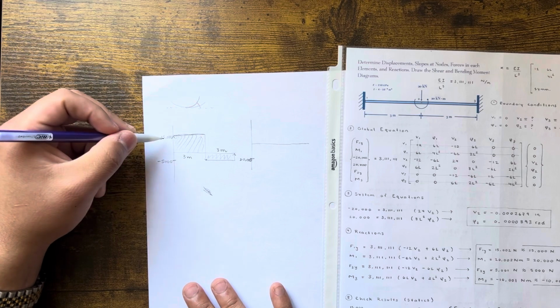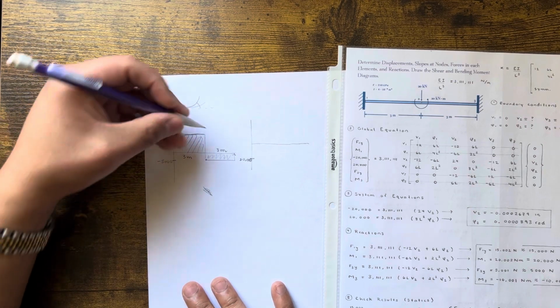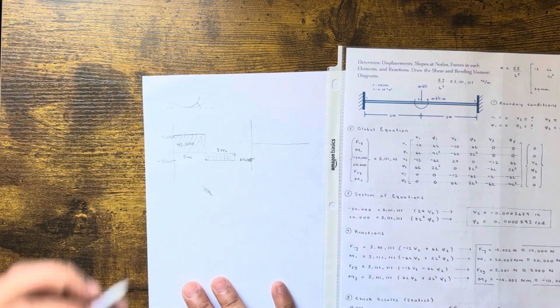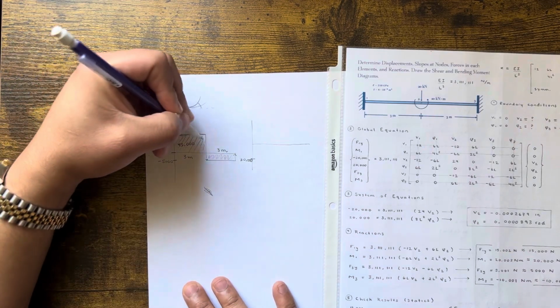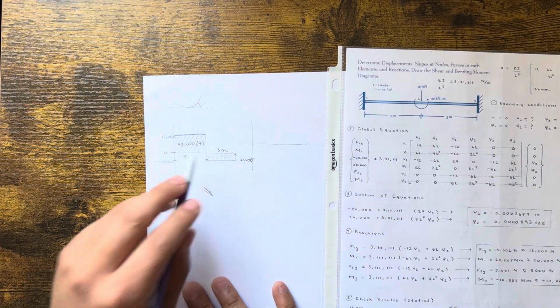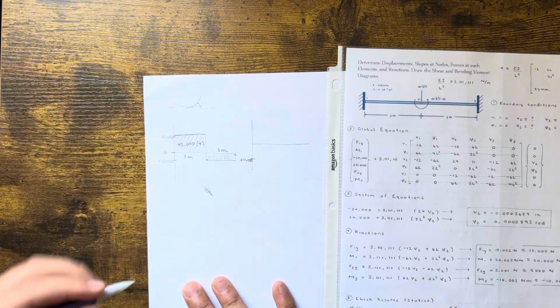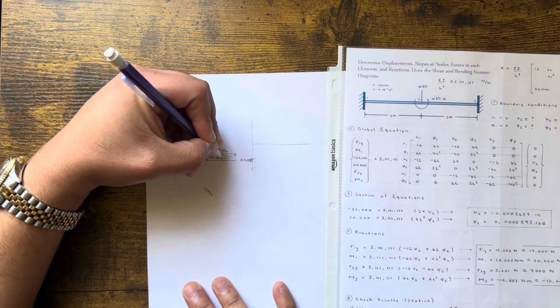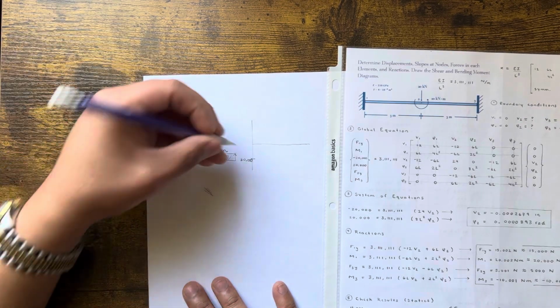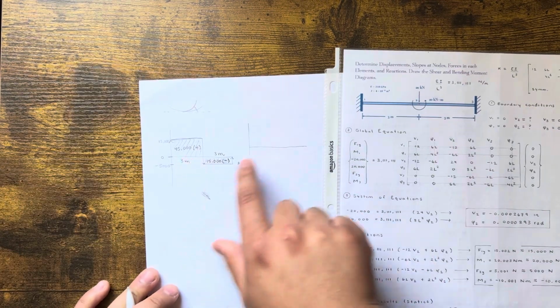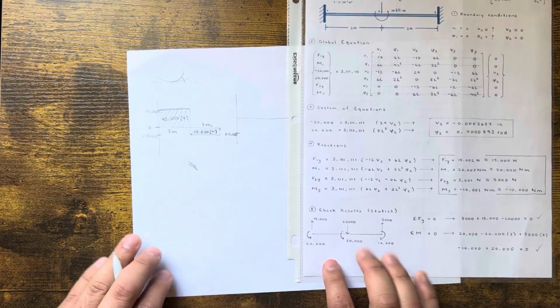So you get the area. 15,000 times 3, that's 45,000, okay? Now, because we're above 0, this is a positive number. 45,000 positive. Let's do the same for this one. 5,000 times 3, that is 15,000. And because we're under 0, that's a negative, okay? Now, we started here at negative 20,000 because it was a counterclockwise moment.